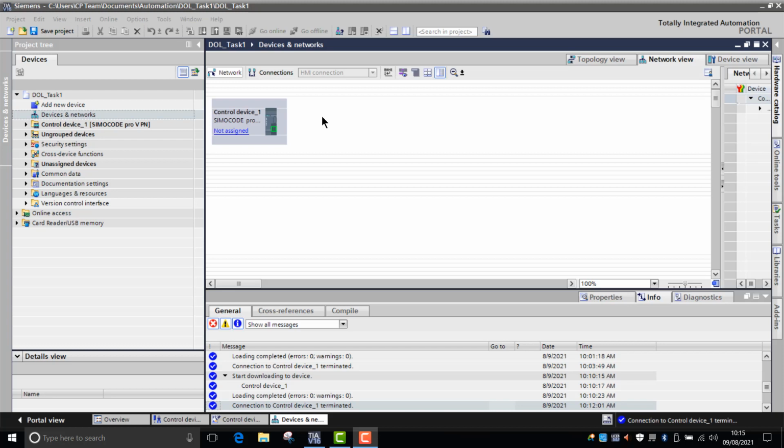And the other thing about monitoring the power factor is that if you have a motor which is operating below the threshold of what you would deem unfit, it actually creates a massive energy loss within the motor. So if you are monitoring power factor of the motor and you set a lower threshold on it, it would tell you when the motor is acting uncharacteristically in relation to the power factor and not acting as efficiently as it should. So what I'll do now is I'll show you how to use it.